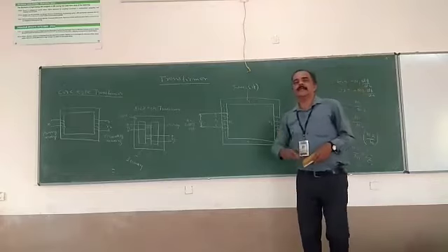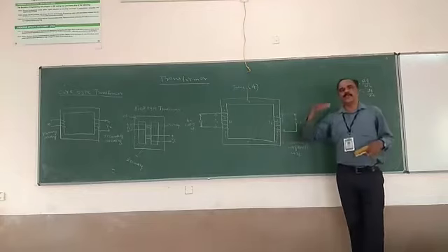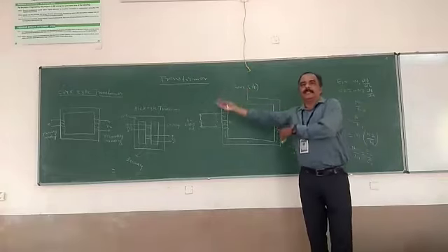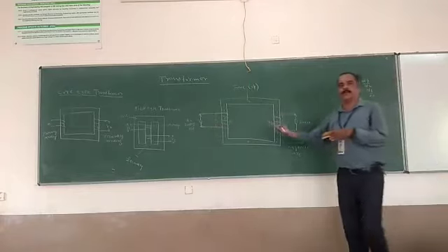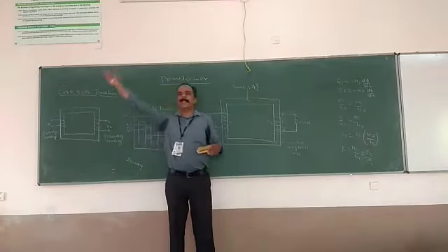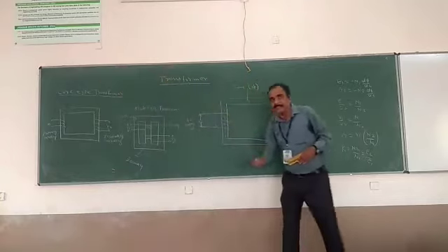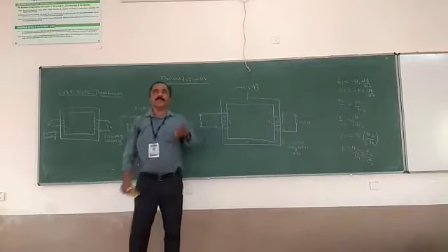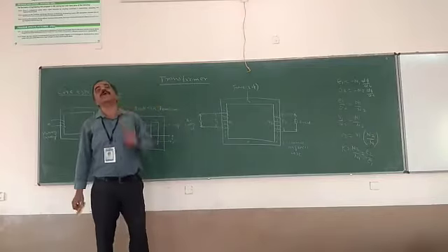Okay. So first, let us see why we need a transformer. In outside you can see, the transformer is the heart of the power system actually. Normally the voltage is generated at 11 kV at the generating station, while at the receiving end, in residential or industry, 230 or 440 volts is needed. It is not possible to generate 230 or 440 volts directly. Normally they generate at 11 kV, step up and send to the transmission line, and it comes to our residential area. There is a substation that again steps down and transfers to our industry area or house area. That's why whenever we need to step up or step down voltage, we need a transformer. That's why the transformer is a part of the power system.